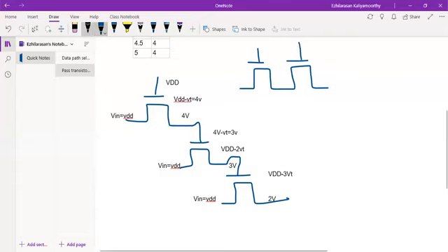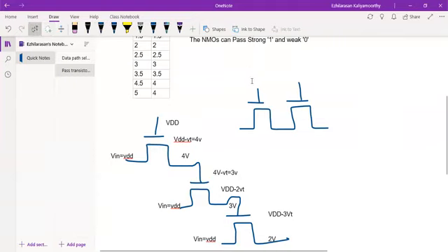This will be your VDD. This will be VDD. Then even this also will be VDD. Now I'll say this is your input Vin. Assume Vin is VDD only. Okay, Vin is VDD. Now what is this here? Here how much maximum will I get? VDD minus VT. In this place I will get VDD minus VT voltage.